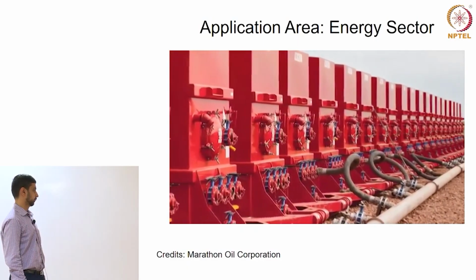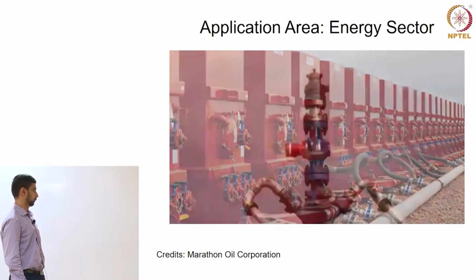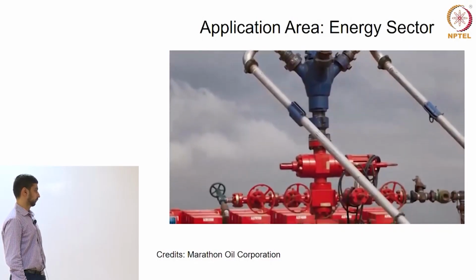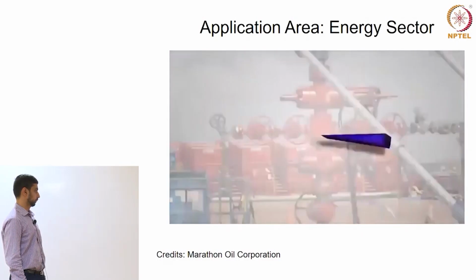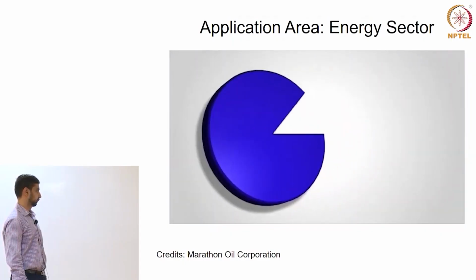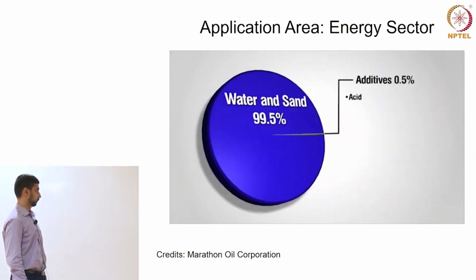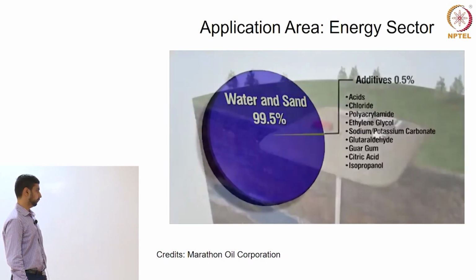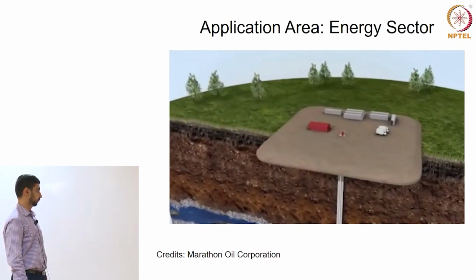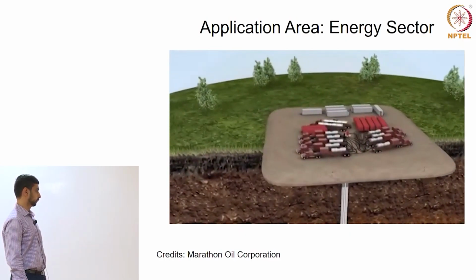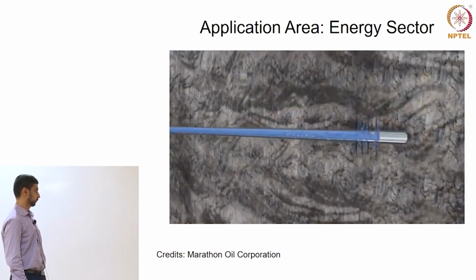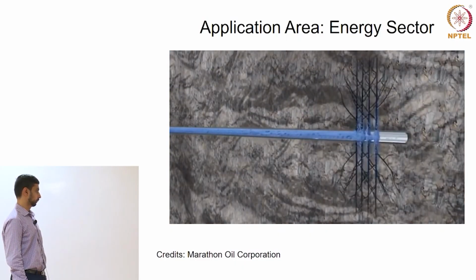deep underground reservoir formations. The chemicals are generally for lubrication, to keep bacteria from forming, and help carry the sand. These chemicals typically range in concentrations from 0.1 to 0.5% by volume, and help to improve the performance of the stimulation. This stimulation fluid is sent to trucks that pump the fluid into the wellbore and out through the perforations that were noted earlier. This process creates fractures in the oil and gas reservoir rock.